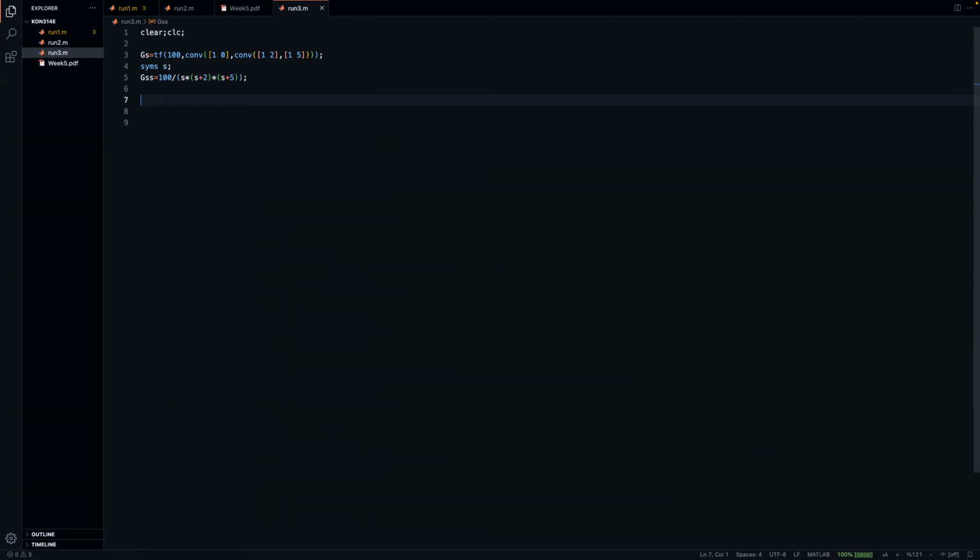So we're going to search for marginal stability, which means that I'm going to define a P-type controller and then look for the closed loop, which would look like K times G(s) divided by 1 plus K times G(s). Then we're only interested in the characteristic polynomial, so I'm not going to bother with the other stuff here.